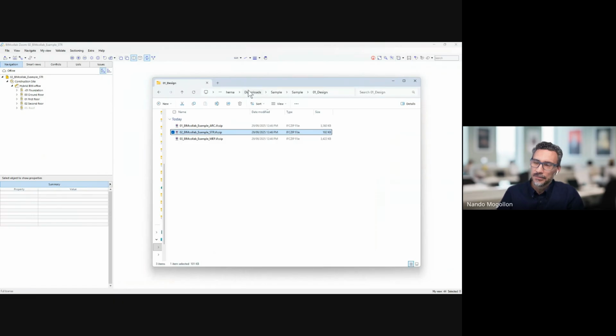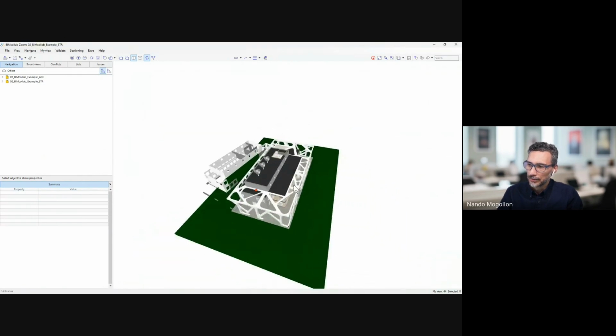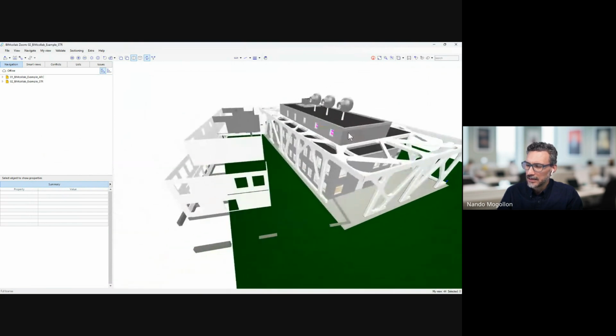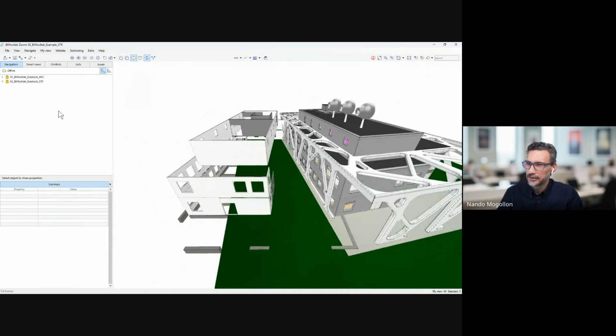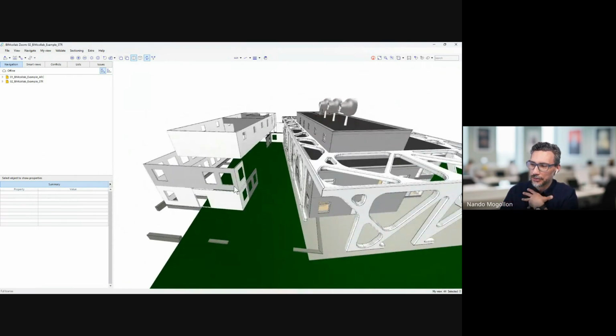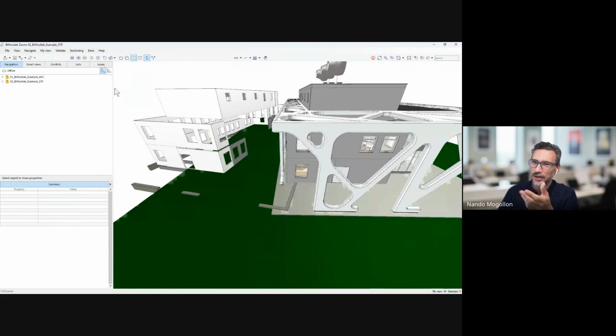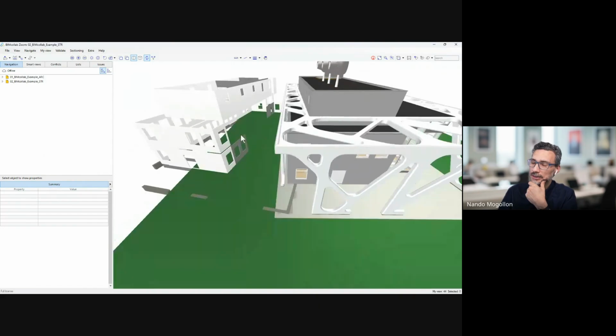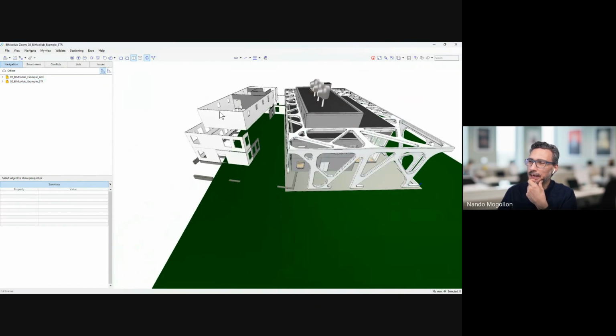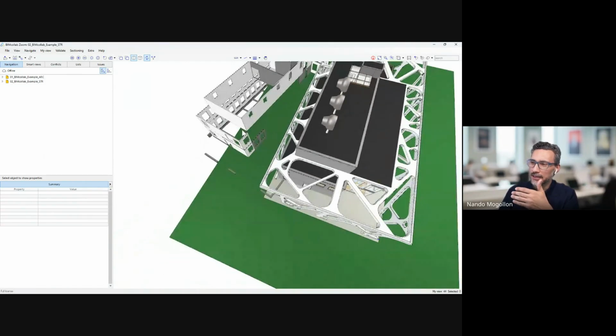And I have exported my own IFC. So what you want to do is do the coordination in here, because it's a lot easier, and just bring in your own IFC to the mix. So now my IFC is that. I've got that file located somewhere else, but again, that's some of my own doing. You remember the origin, I was making the assumption that it was up here. It is not. So I'm going to correct the location of that. And now you know that if you have to move that, in this case, it will be moving south 22,500 and rotating to whatever rotation there is.